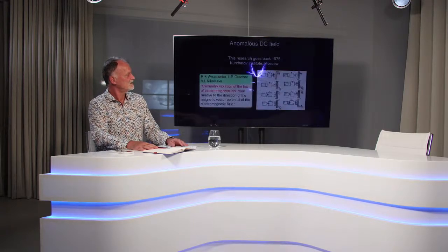I can tell you also that we see a lot of very strange effects. For example, this is an infrared camera, and we are measuring the temperature of the surrounding materials, the wire itself, and so on. And we realize that if there is a metallic object close to this transformer, then although it's completely cold, if you touch it by hand, you will get burned. Right? Things like that. Very nice. So I think we can move on, if you allow me.